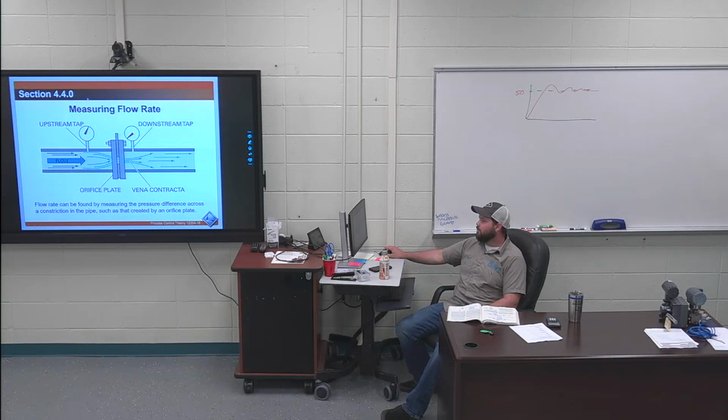And we can connect a differential pressure transmitter to the upstream tap and the downstream tap, and then it can do calculations. Based on the hole opening and the pressures, it can determine a flow rate, right? So measuring flow rate, you can see the upstream tap as this laminar flow is coming in, it's getting constricted, which is causing the pressure to go up. On the backside of this, it's got all the area in the world, so our pressure is down.